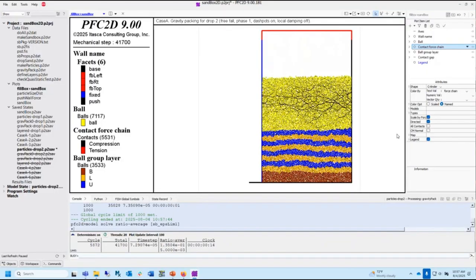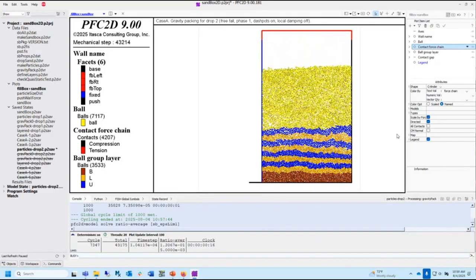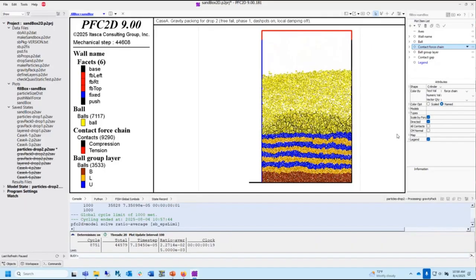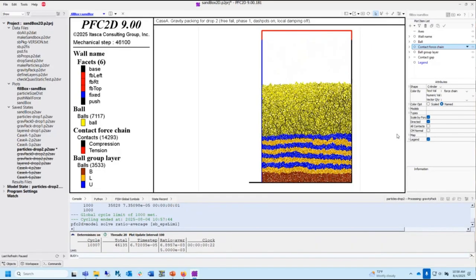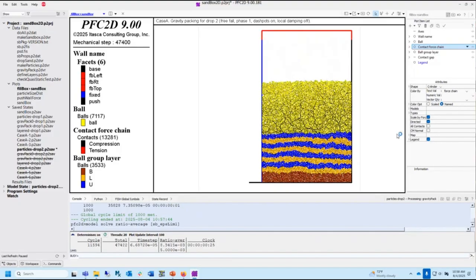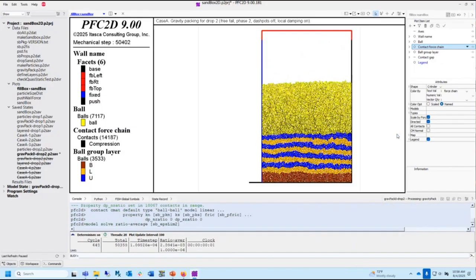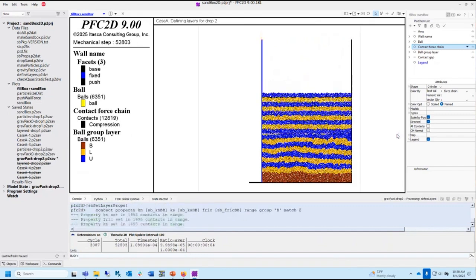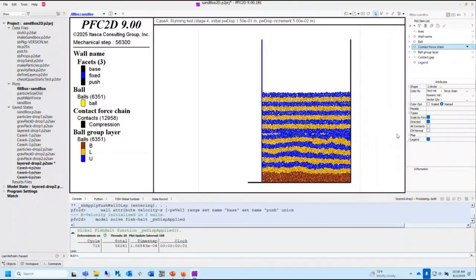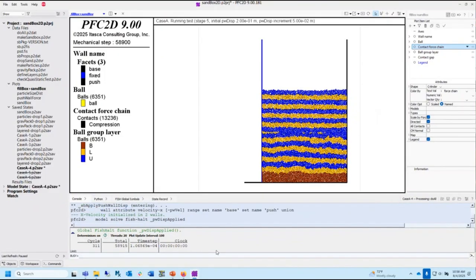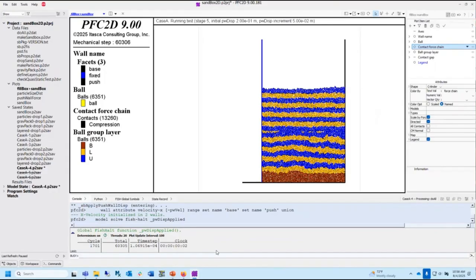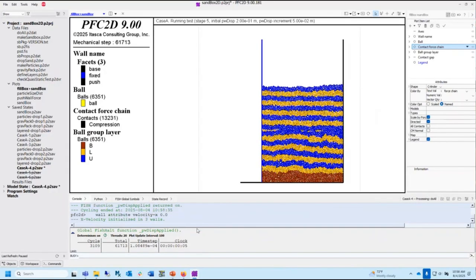And the fact that it compressed that sand is kind of like a shock absorber. That new material didn't quite bounce as high. Now we're going to do the same thing. Once this gets to equilibrium, we're going to define new layers, and then push. We're doing this in 3D as well. But again, notice the time step here, 1e to the -4. That's what it was in our first system, because that's about as small as you can do without getting too much overlap.